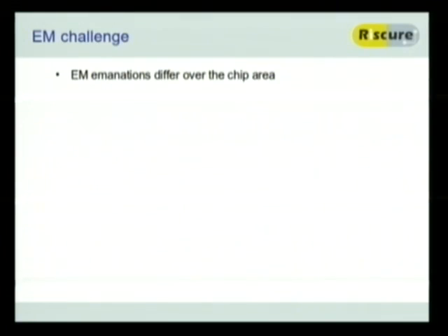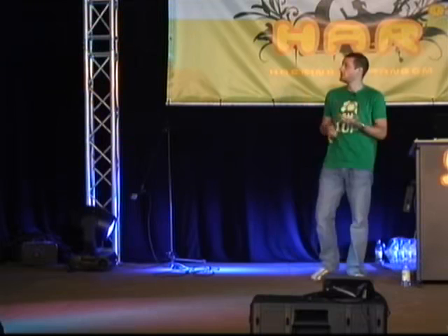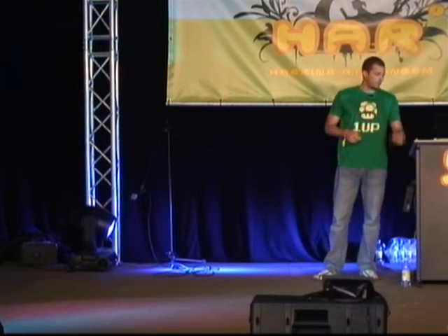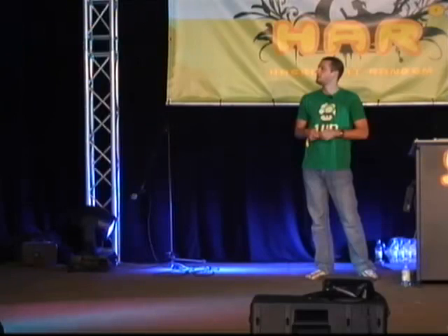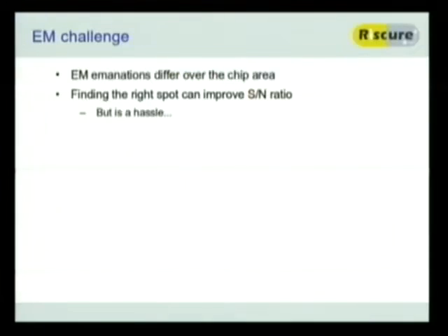Now, for EM, we have one more challenge than with power. With power, we're measuring the whole power over a whole smart card, let's say. But EM signals are actually very localized, and it really depends on where you're measuring what you're going to see. So this is a bit tricky to find this spot, and then we used to do it by hand, just move it and see what your signals are.